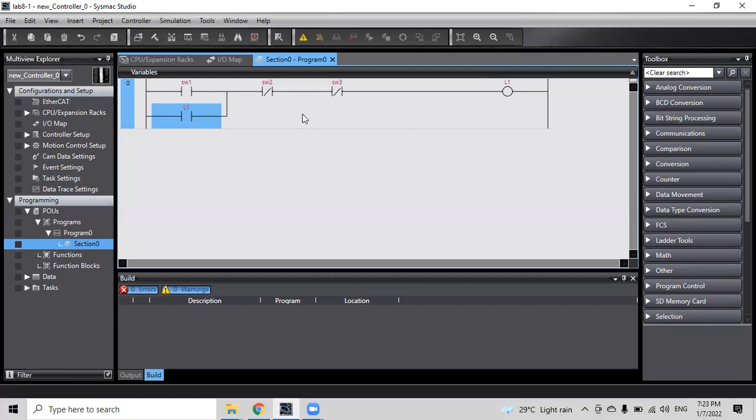Then, for example, you have a switch with a pulse signal, you send a pulse signal to this one. If we don't have this, it's just a pulse: you start the motor with a pulse signal, but when you release the button, it's off. That's why we need this one. We call this one a latch.